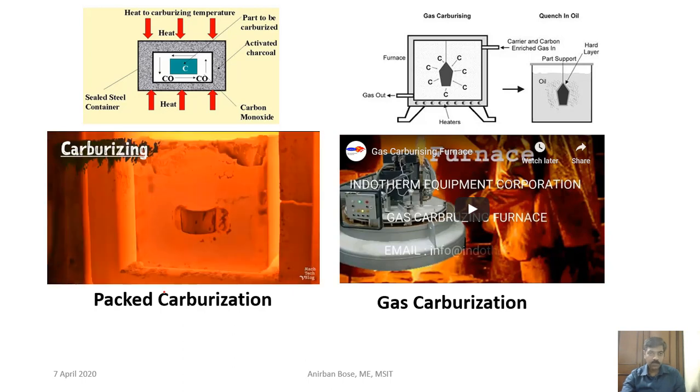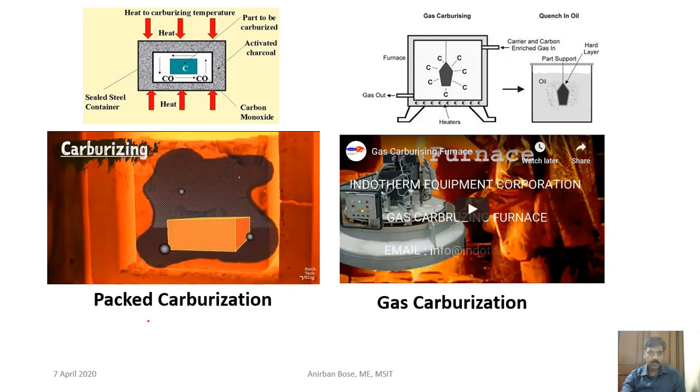But inside the furnace, there's a bit of science magic happening. Carbon-rich gas comes in contact with the metal surface, breaks down, and some amount of free carbon is dissolved into the hot steel. Time, temperature, and the composition of the atmosphere all affect the rate at which carbon is absorbed and how deeply it penetrates into the steel. After 8 hours at 1700 degrees, the carbon should penetrate 1/16 of an inch into the part.